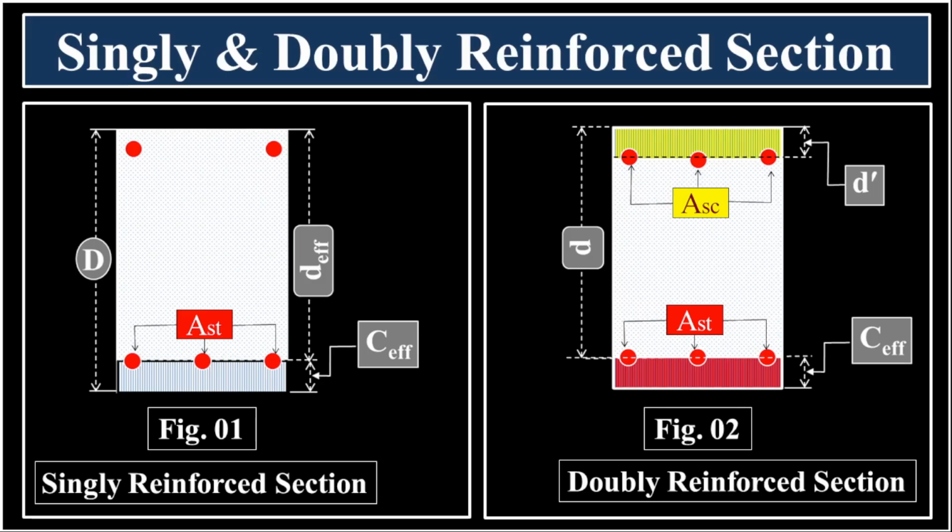The full form of PT is percentage of steel in tension, and that of PC is percentage of steel in compression. By reinforcing both the compression and tension zones of the section with steel, the overall dimensions of the section can be reduced. Consequently, we can decrease the depth or width, or both, to fit the structure within a confined space.